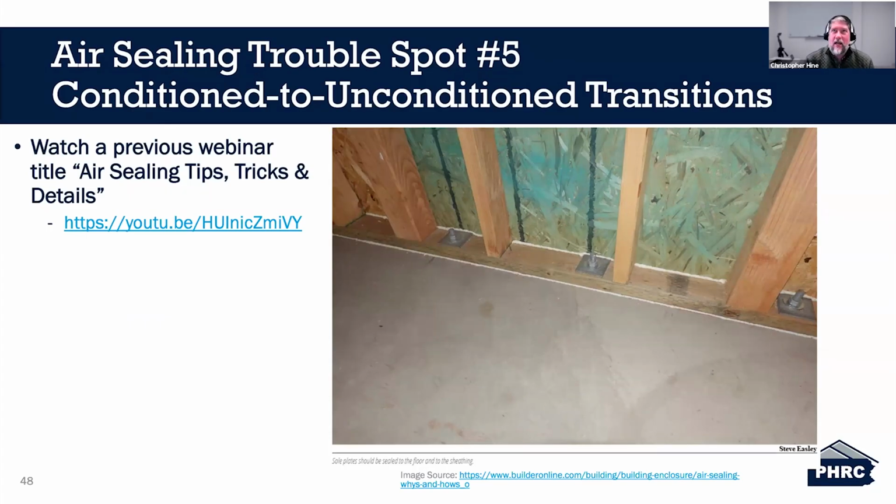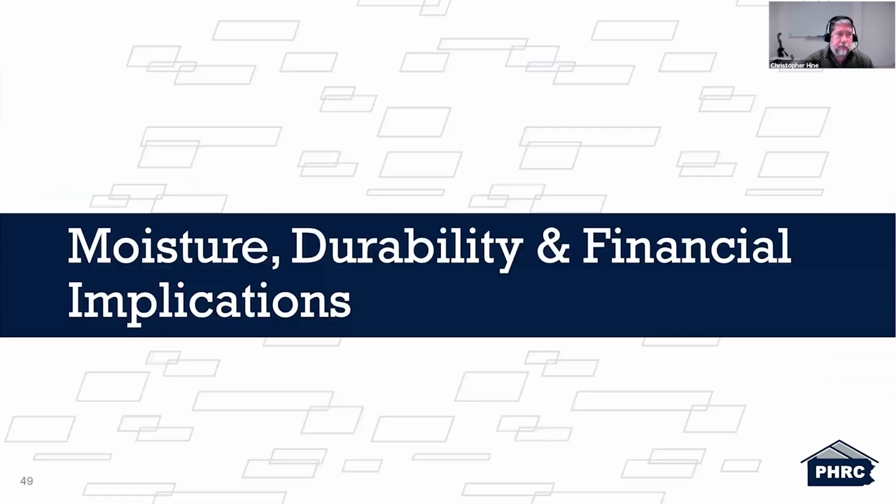And if you have a light colored carpet in your house and you walked over and you saw, in the intersection of the wall and the carpet, a dark, dirty strip between the drywall, it's on the carpet itself. What's actually happening there is air is leaving or coming in through that area, and it's using the carpet as a filtration system. So that's a big source or indication for a leakage area.